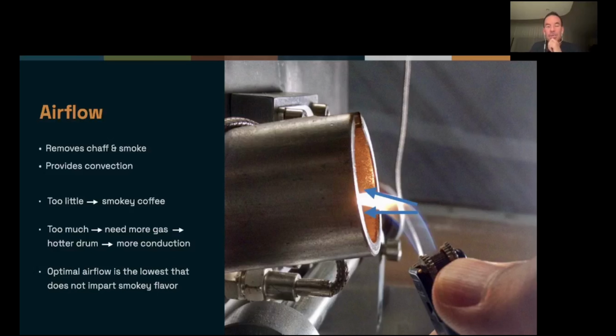Oh, okay, I'm sorry, I misunderstood the question. So if at the end of the roast the airflow is so high that it's pulling out the lighter during the lighter test, then you definitely have higher airflow than you need. When it comes to very large machines, like let's say 60 kilos and larger, the cigarette lighter test tends to pull a little bit harder, tends to be kind of a horizontal pull more than a 45-degree pull. With machines smaller than 60 kilos, you can usually achieve a 45-degree pull pretty easily.